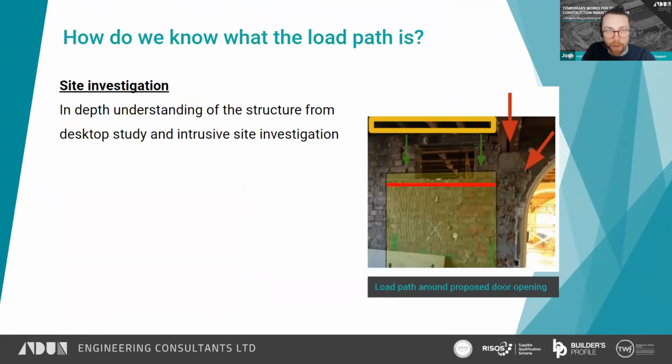But how do we know what the load path is? Well, we need to have an in-depth understanding of the structure, which is developed from a desktop study and intrusive site investigation. And it's important that a competent person reviews this information and is also confident in their conclusions. Sometimes the simplest operations, such as creating a door opening, as shown in this example on the right-hand side there, can include some very tricky load paths which must be considered, especially when you're altering a structure which has already been altered before. There are some complex load path arrangements that need to be properly considered.